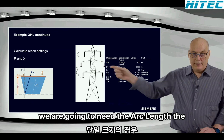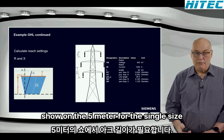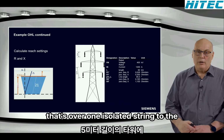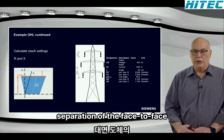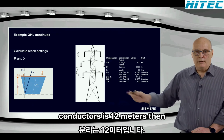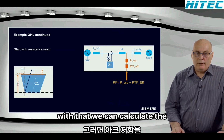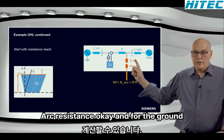For the resistance we are going to need the arc length as shown there, 5 meters for the single phase. That's over one isolator string to the tower, the 5 meter length, and for the separation of the phase-to-phase conductors it is 12 meters there. With that we can calculate the arc resistance, okay?